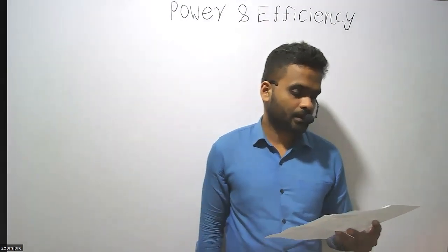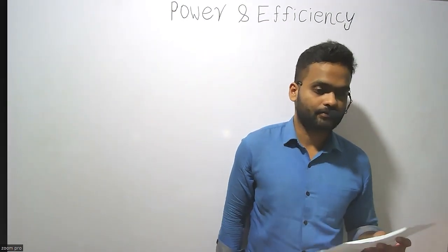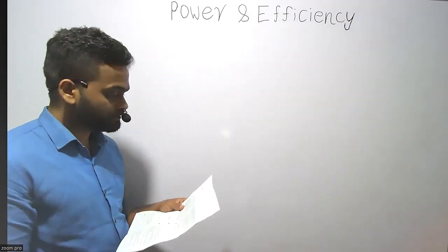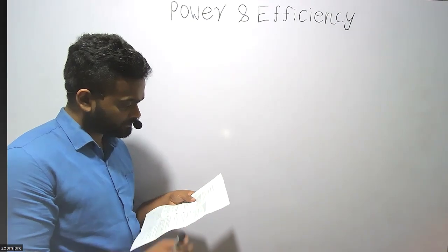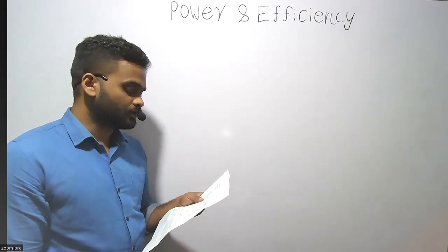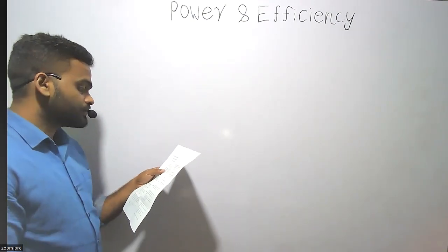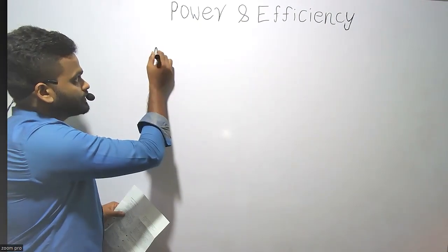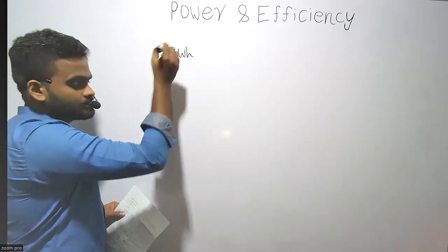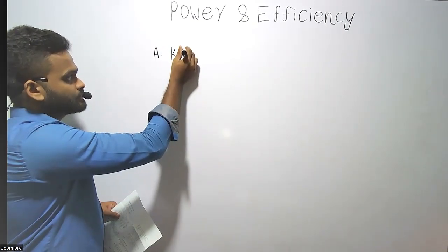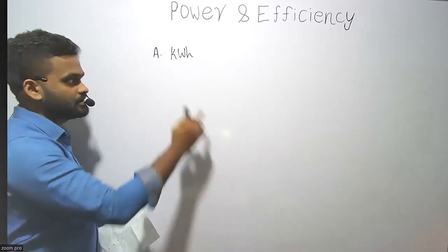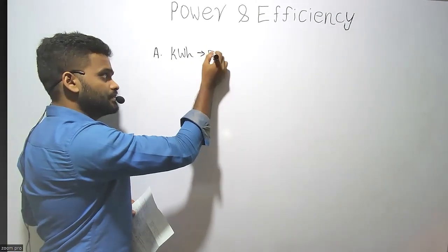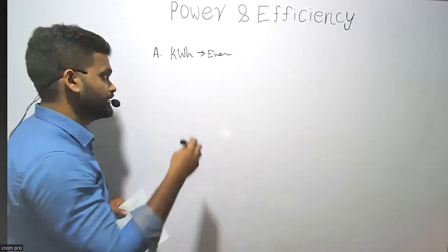Right. We'll try the first one. We'll get it done, right? Just read the question. Consider the units below. So what they ask is a unit of power. Okay. So for option A, we have kilowatt hours. Just because there's watt here, it doesn't mean that is a unit of power. This is actually a unit of energy, right? Energy. Let's see why that is.